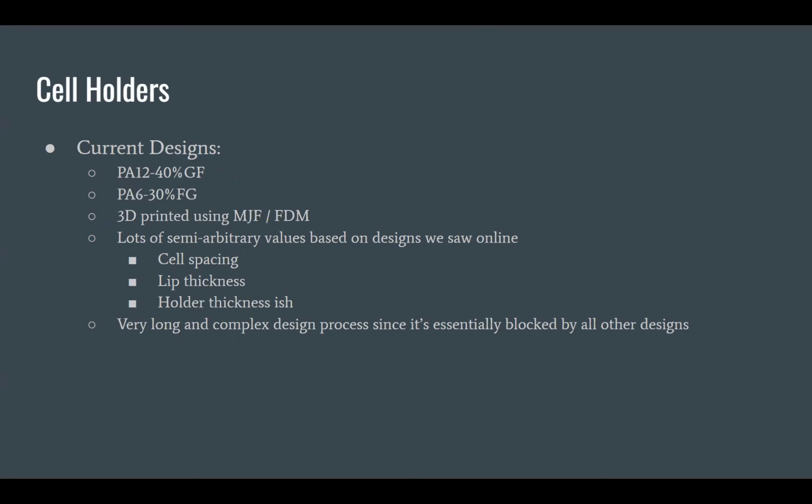Yeah, so obviously our current design, just the super high level stuff: we have two different types of plastics, with different levels of glass filledness, depending on if you're looking at these guys, which are the 8 by 10 segments, or the long guy, which is the 4 by 20. So obviously they're using different types of 3D printing, like I said, MJF versus FDM.